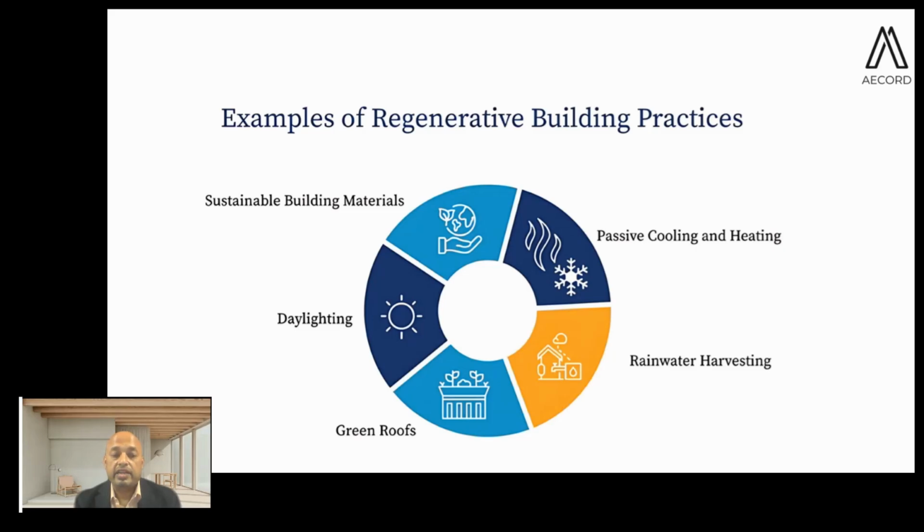So coming to daylighting, definitely we have achieved in most of the projects 25 to 30% on an average. Our annual energy consumption of lighting can be reduced by integration of daylighting into the project. Now, does daylighting integration happen after an architect has already designed and a green building consultant comes to it? No, it does not happen that way.